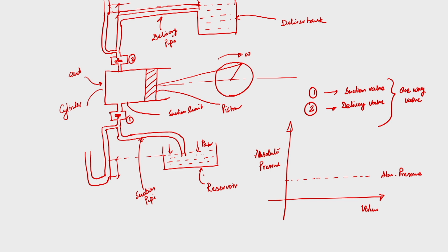Now, when the piston has reached that outer limit point, the front open side of the cylinder at the limiting condition, the cylinder will be filled up with the liquid, and the valve will try to remain seated over the suction side, since it is a one way valve. The force acting on the valve will be less because of the less driving potential.